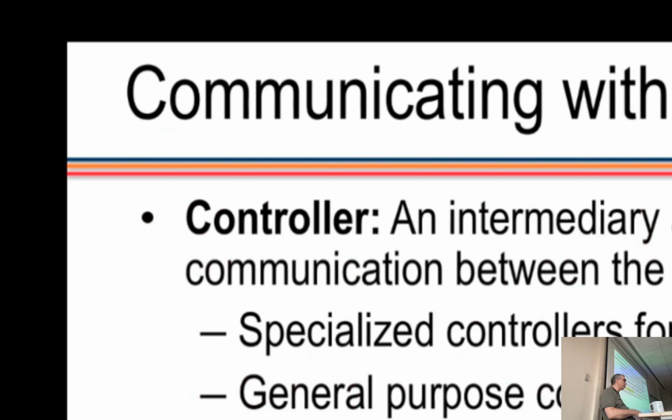Memory-mapped communication is more advanced. It is more advanced, elegant, and also simple. It's easier to understand. You don't need additional instructions, additional modifiers. You write to the memory, and it becomes output. You read from memory, it becomes the input. It's outside.